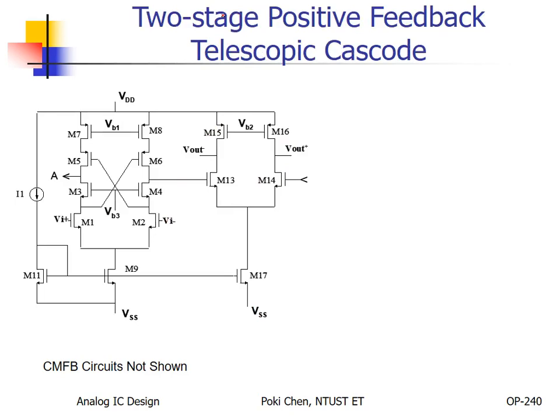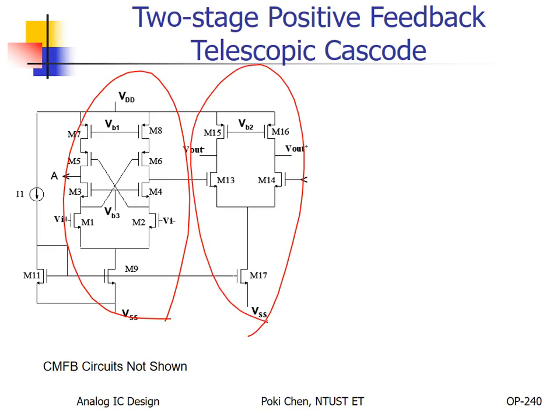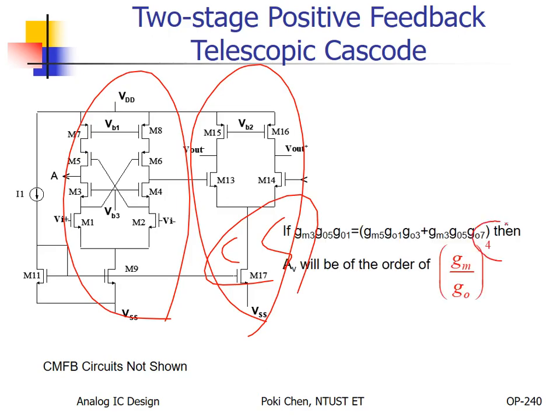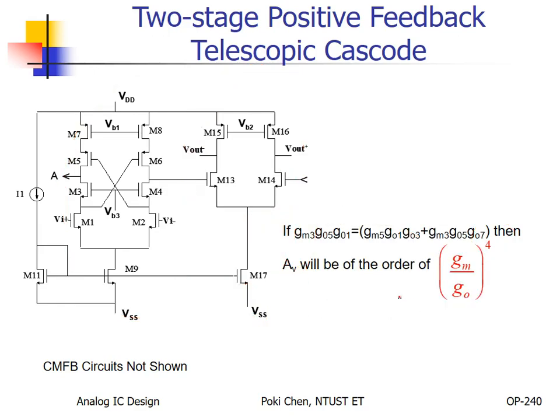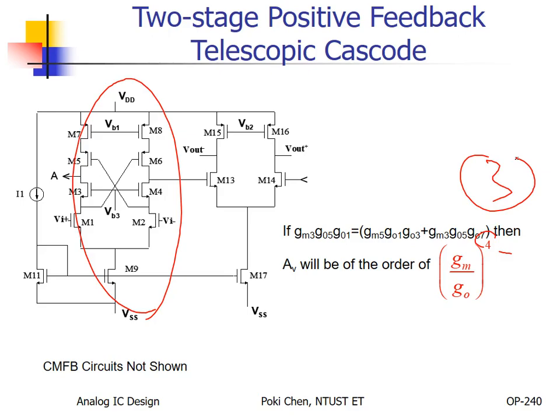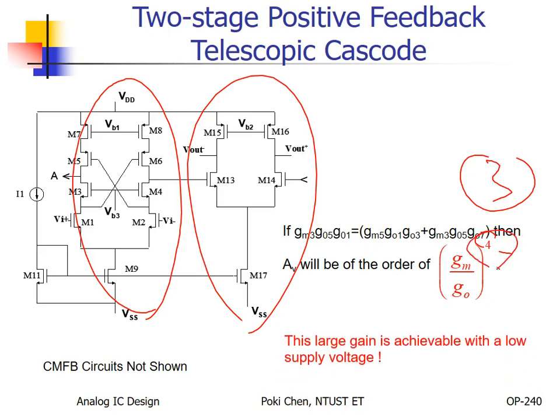If you think the gain of the first stage is still not good enough, then you can apply the second stage. And what is the second stage? The high gain stage. Actually, again, it is common, some kind of common source configuration. Then one more order according to this. So we can see the power of positive feedback. Even only for the first stage, you get third order to enhance the gain. So the second stage only provides an extra order to make it full. All right. Anyhow, let's go for it.